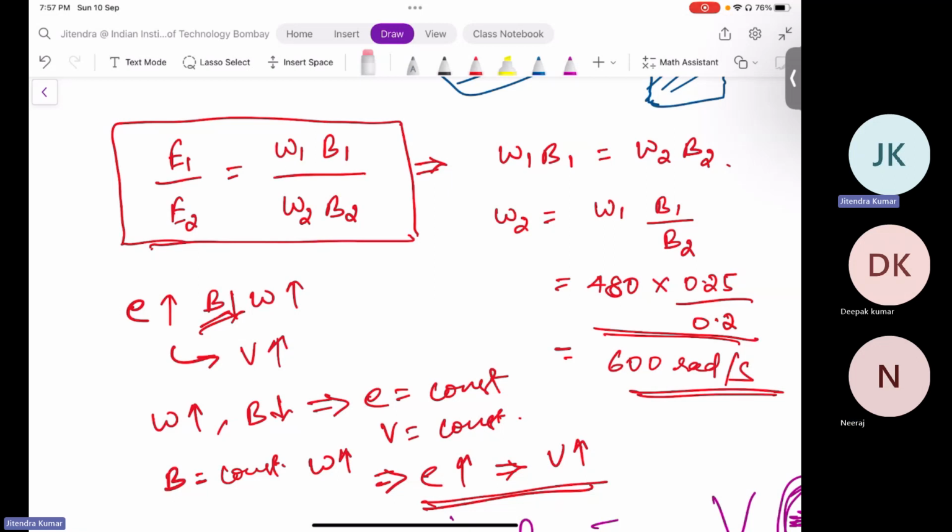Just with the help of switches, without any help of brushes and commutators. Okay, sir. But what will be the impact? That is an important point to note and take away from this lecture. What will be the impact if you are doing field weakening? You are reducing the flux, you have increased the speed to maintain the voltage.